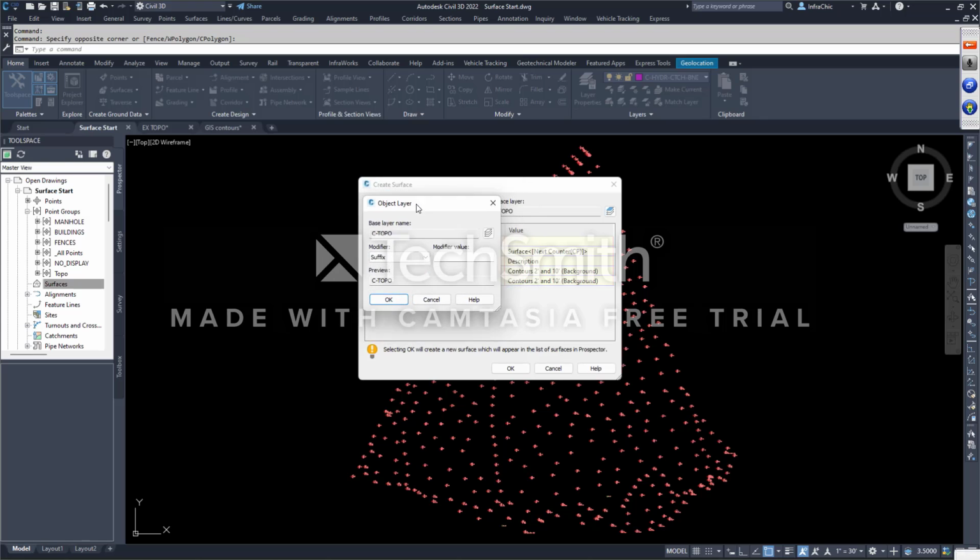And my rule of thumb is I'm going to put dash asterisk. Asterisk is your wildcard. It picks up the object name and puts it after the dash. So it'll say C-topo dash, whatever I enter for a name right here. Okay. So right now it says C-topo dash asterisk. If I had already filled this out, it would say whatever this name is. I'm going to hit OK, and it stays there.